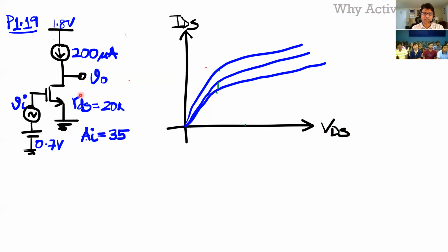So if I change the bias voltage in a large signal manner, this is how the curves will look, right? We covered that when we covered the transistors. These three different curves are for three different VGS. When I'm giving a small signal, the VGS is going to change, so these are the transfer curves for each one of them. I've exaggerated the output impedance by showing that it's a slope, it's not constant. Now the reason we get gain is, if we want to find delta Vi, the input, versus delta V out, which is really the gain,